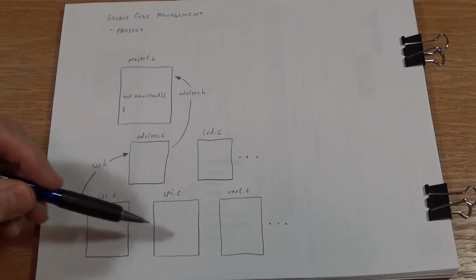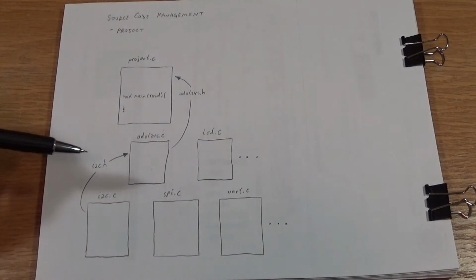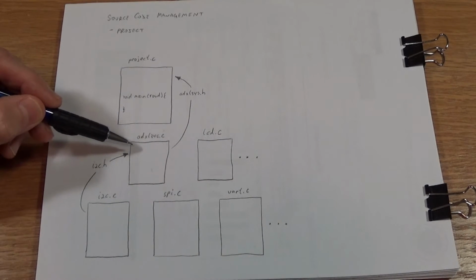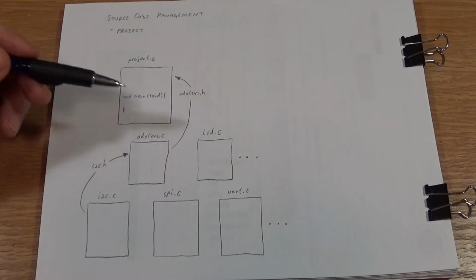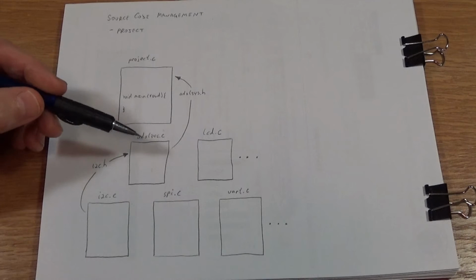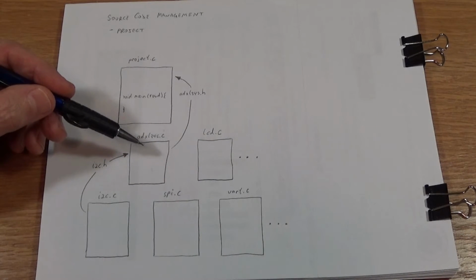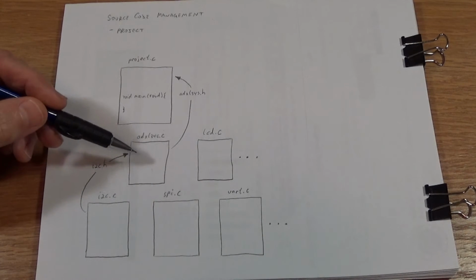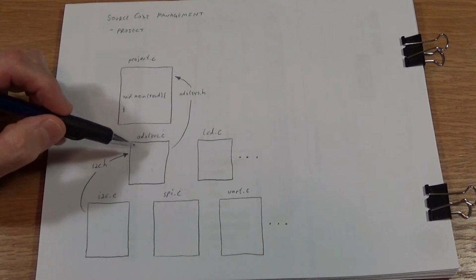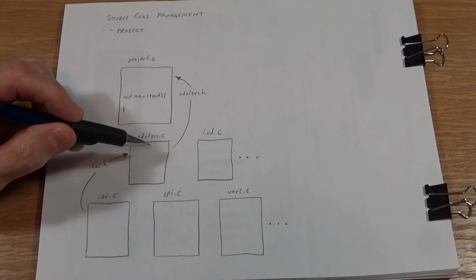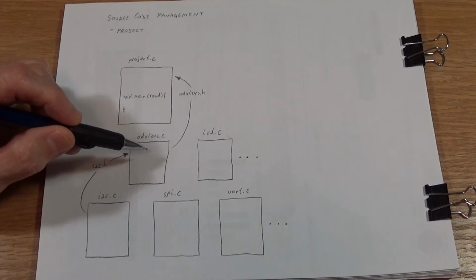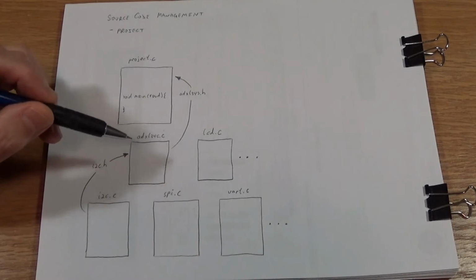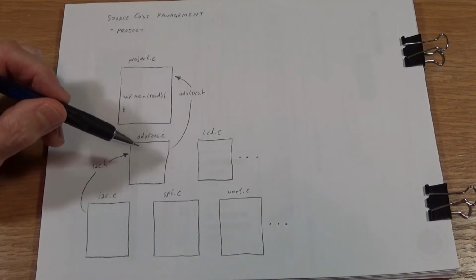Now again, these boxes here represent separate files. I wasn't very clear on that. So this is the driver code for the accelerometer, for example. ADXL345 is a very common accelerometer. You can buy breakout boards for them everywhere on the internet. They're dirt cheap. And it uses the I2C interface, or I2C protocol, for communicating. And in here you can put routines that read the X, Y, and Z, or Z if you're in the US, data for the 3-axis of the accelerometer.